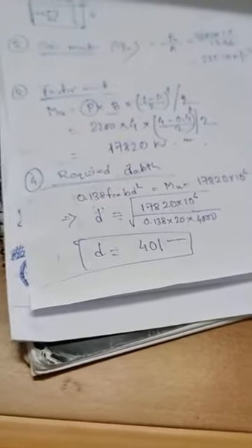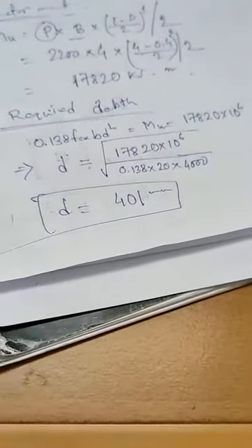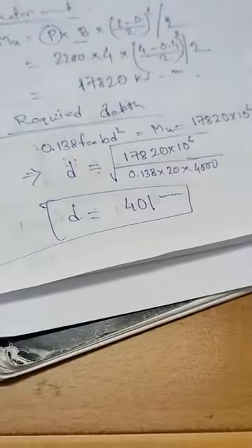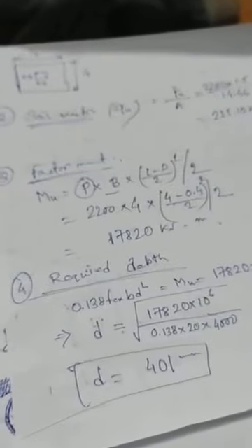So hence you can solve these desired values. Now some steps we also have to proceed with, like proportioning of the footing for the column, check for the bending moment, check for one-way shear, check for two-way shear, check for bearing stress, and check for development length as well. Okay, in the next class we will continue. So that's all for today. Thank you.